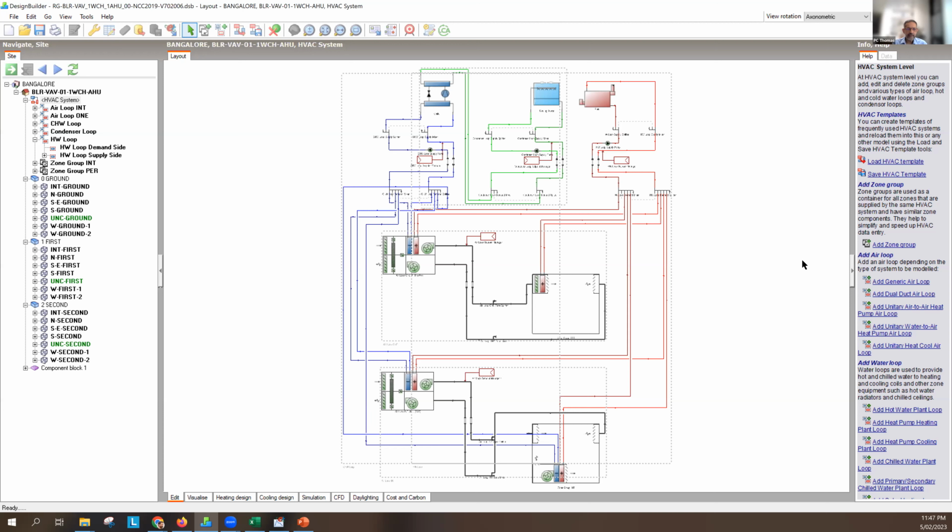Mixed mode buildings are fine in dry climates. In humid climates, they're a bit more difficult, because when you open up the building to allow external air to come in, it brings with it humidity. The next time you turn on the air conditioner, if you're not careful, temperatures of surfaces will drop below the dew point and you'll get condensation.